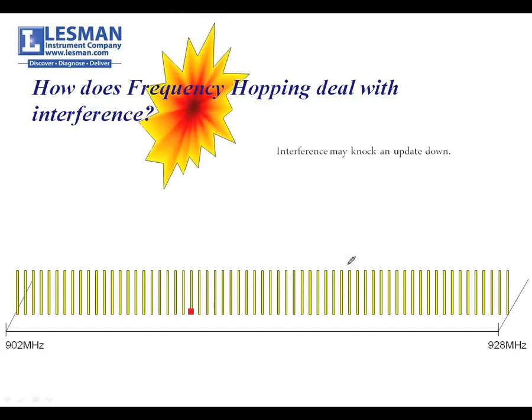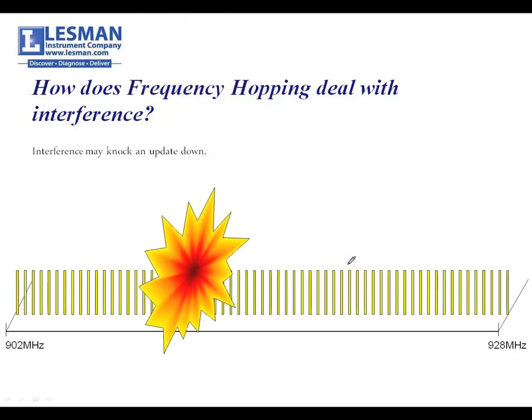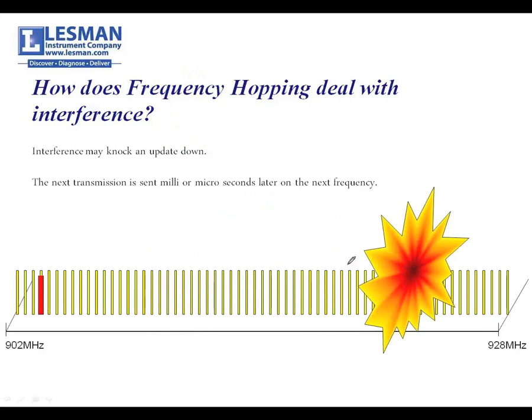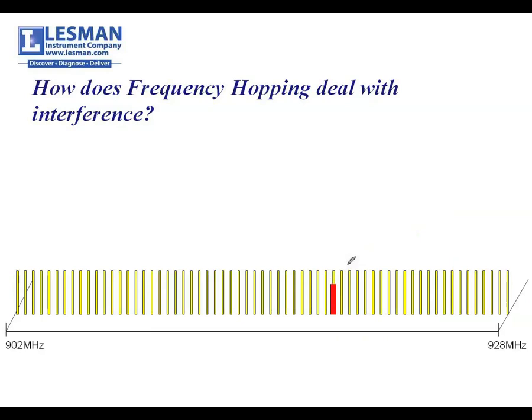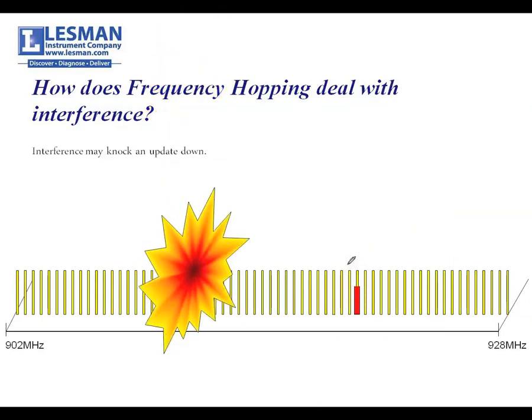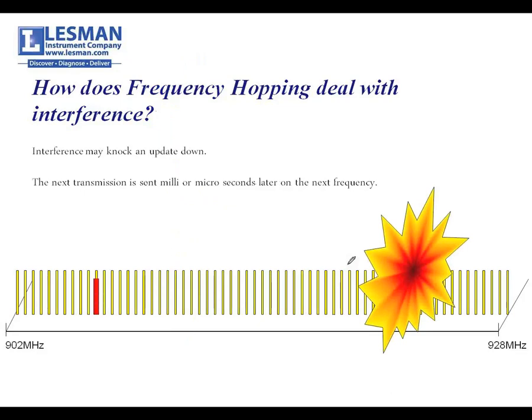We're communicating, we're jumping around a 900 megahertz band, and you can see at some point there's a collision, and you lose that piece of data. Now, what happens in the real world is when you get that collision, it doesn't mean that you completely lost communication. It means that that bit didn't come through, and the receiving radio is essentially going to say, I didn't hear you, send it again. Okay, so in a situation where you're getting lots of collisions, you'll have your communication slow down significantly.